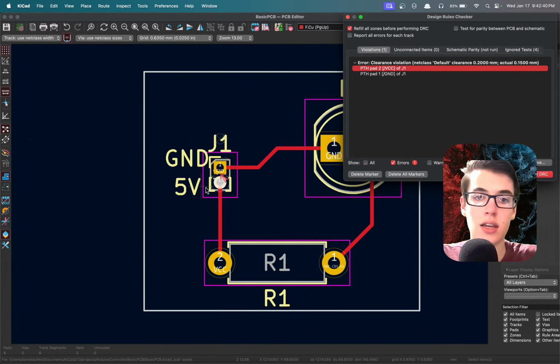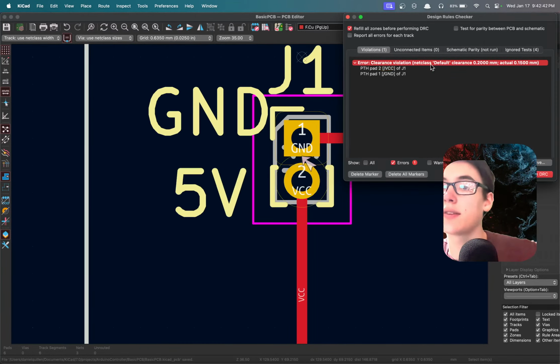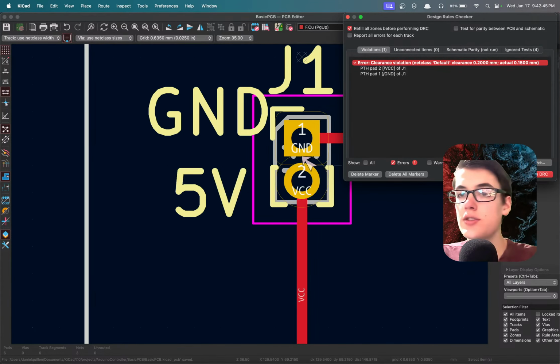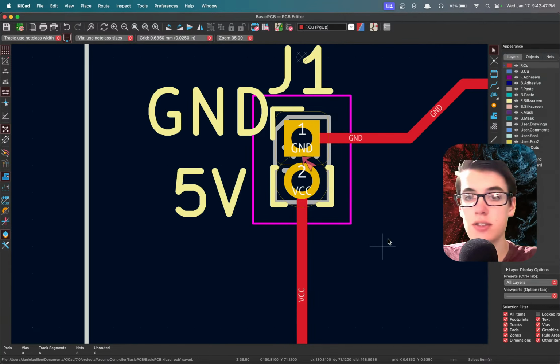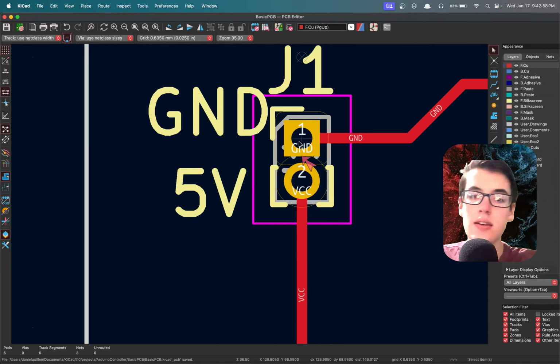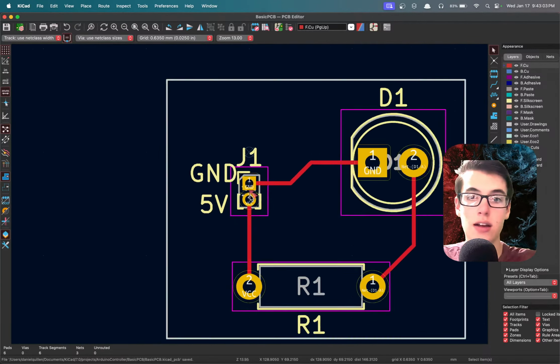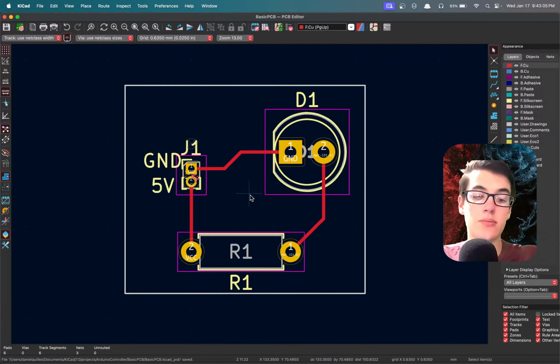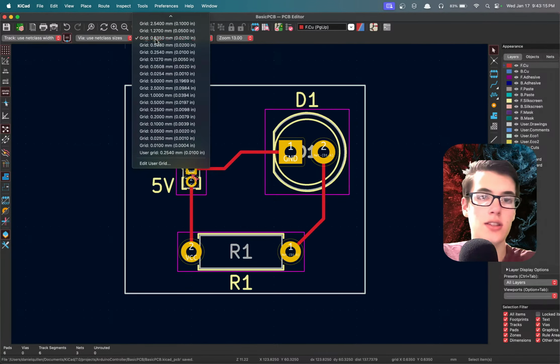the error here is we don't have enough clearance. There's supposed to be 0.2 millimeters of clearance, but there's actually only 0.15. So this is actually an issue with this footprint for pin headers that we've designed. It should be because these two pads are placed too close together for our tolerance to allow for that. So we need to mark the tolerance as more precise, so when we go to actually manufacture it, it uses more precision to make sure that it's actually accurate.